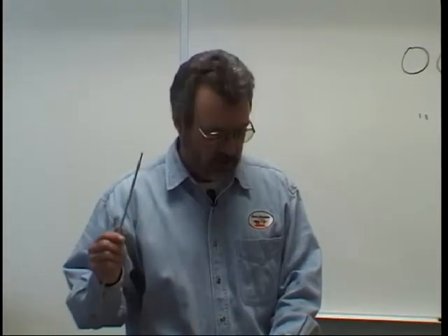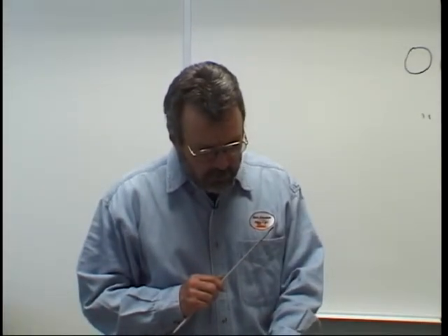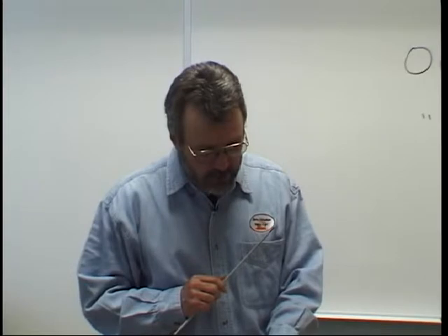Flipping the page, bottom of the second column on page 782, there is a considerable refrigeration effect. I wanted to point this out to you because this happens with both gas tungsten arc and gas metal arc. A considerable refrigeration effect in the high pressure section of the regulator. Sometimes on very heavy duty cycles, frost forms on the outside of the regulator. This indicates only that the regulator is getting cold.